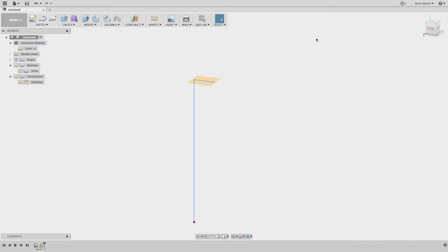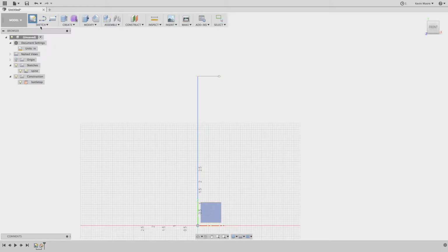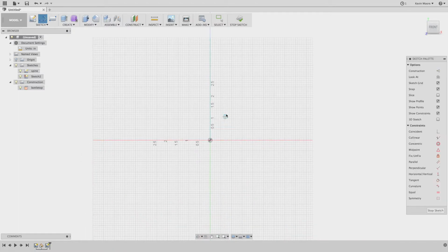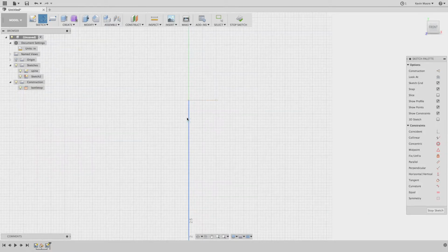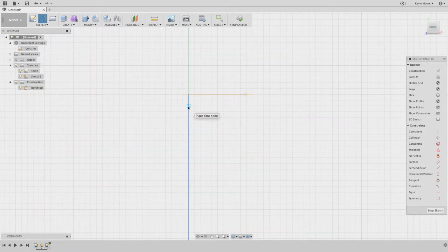So now I'm going to go back and make another series of lines that I think I'm going to need. Let's go back to my sketch, create sketch, line, and I'm going to click on that so that I'm still drawing here. You'll see now I've got a sketch 2 here, and then I can choose where I want that next construction plane to go.